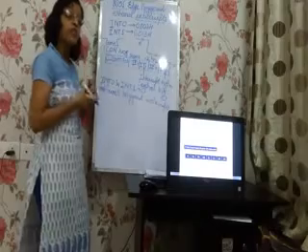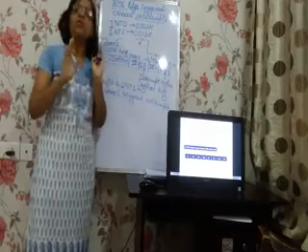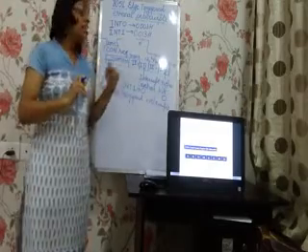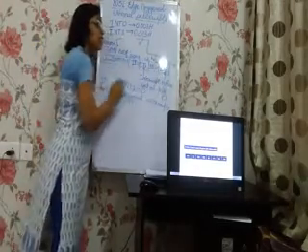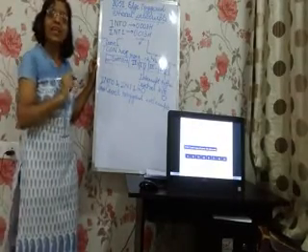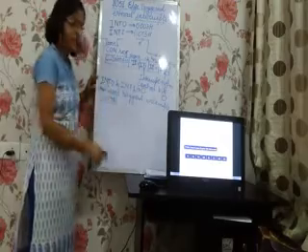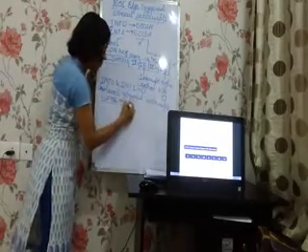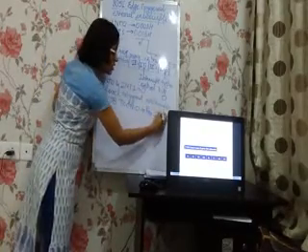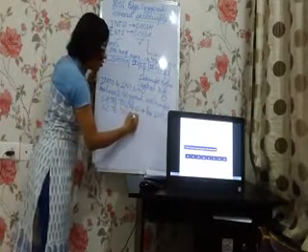Now if we want to configure them as edge triggered interrupts, suppose for an application we want to detect a particular signal or an interrupt on the falling or the rising edge, then what do we need to do? We need to define INT0 and INT1 as edge triggered interrupts. To do that, we simply need to give an instruction: SETB TCON.0 for INT0, and SETB TCON.2 for INT1.